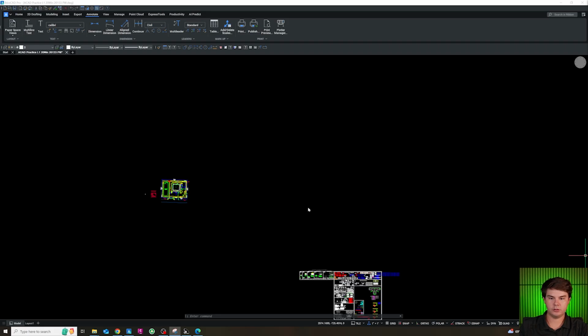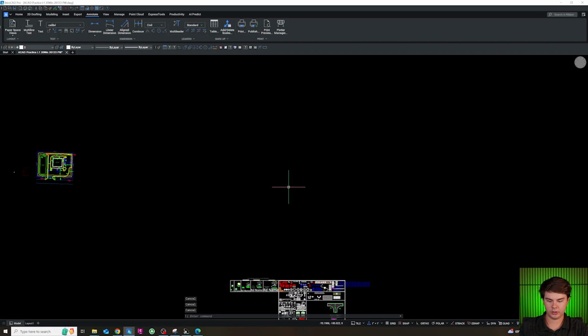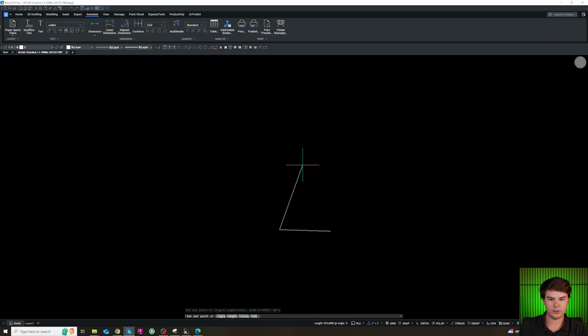So typically I'll start off with drawing the property lines. To do this, you'll do L for line and click a point, and then you'll hit @, and then however long it is, 280.5 feet, less than, and then you'll do the metes and bounds, so north 88D 17'00" west. And now I'll just continue that process as I draw the rest of the lines.